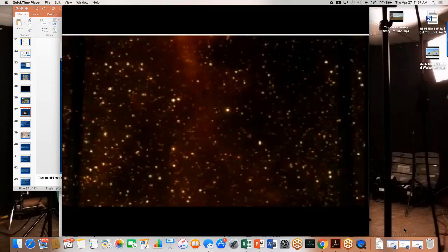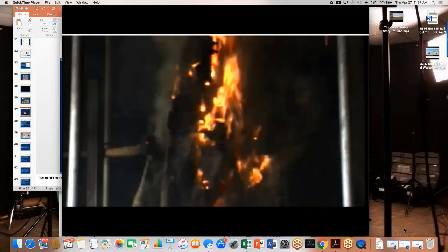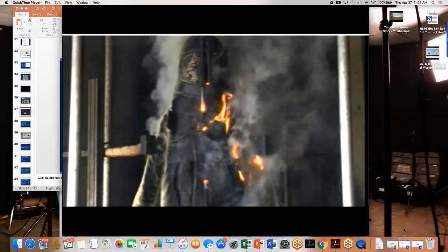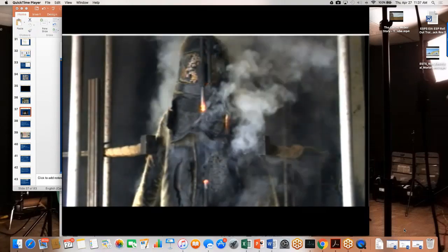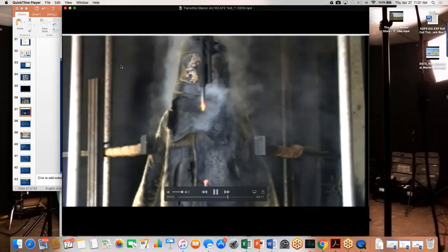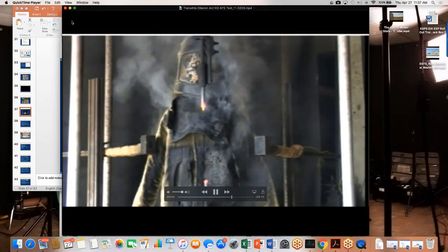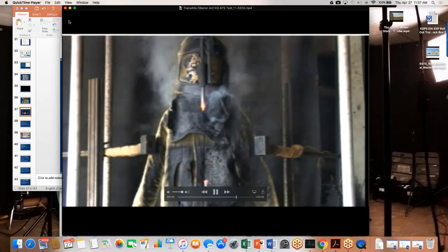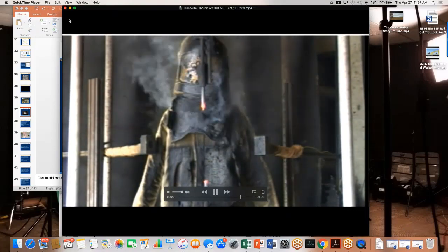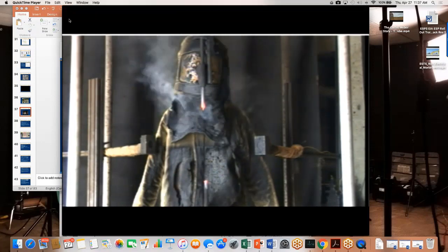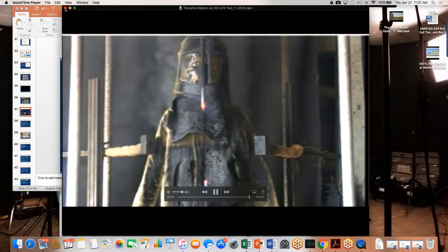We wanted to make sure that it would perform with the coal that was in it and contaminating it. What we want to see is that the after flame self-extinguishes in a relatively reasonable amount of time, which it does. We only had a test of 1. We couldn't afford to do any more. These tests are expensive. But the coal looks like it flashed off, or it wasn't contaminated to the level where it degraded the performance of the arc flash suit.